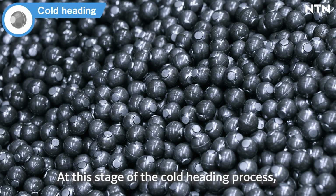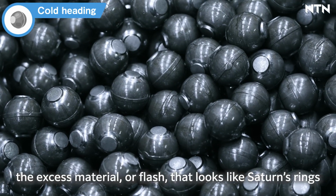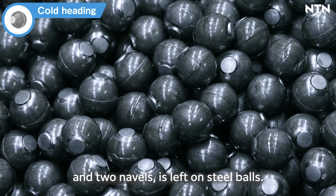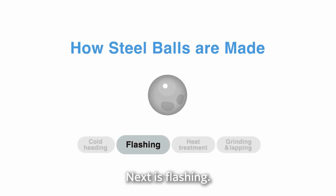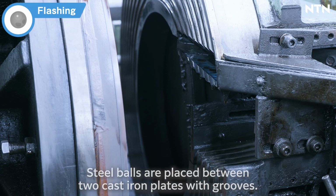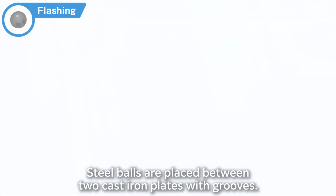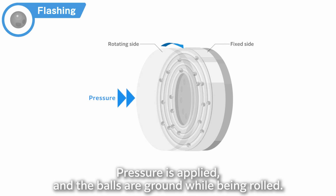At this stage of the cold heading process, the excess material, or flash, that looks like Saturn's rings and 2 navels is left on the steel balls. Next is flashing. Here, the flash left from the cold heading process is removed. Steel balls are placed between 2 cast iron plates with grooves. Pressure is applied and the balls are ground while being rolled.